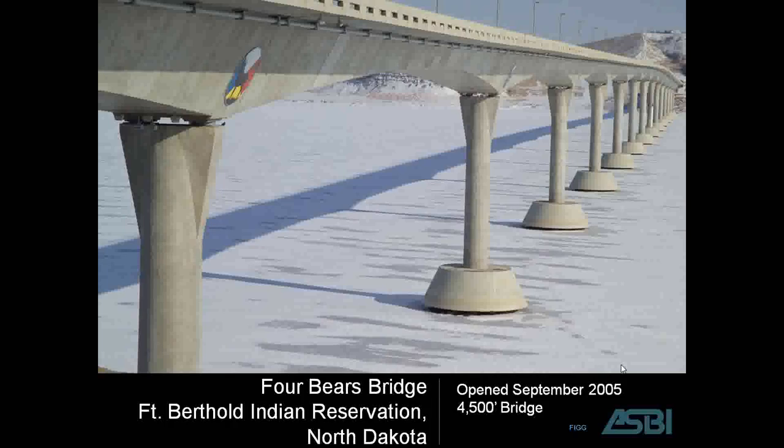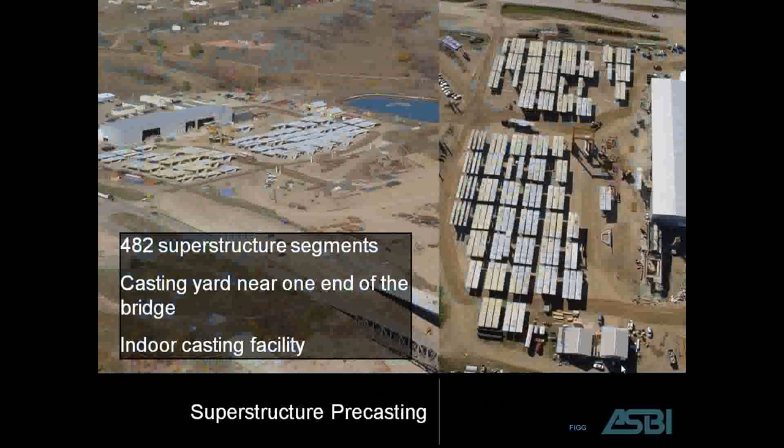This bridge also has an integral wearing surface, and you'll hear me talk about this throughout the presentation today. Several of the bridges I will show will have this type of wearing course. It's a 2-inch additional concrete depth that's applied to each segment, and that acts as the integral wearing surface. After the bridge is constructed, it's ground down for rideability, and that integral wearing surface provides protection from chloride intrusion, and in the future could be removed and an overlay applied if it ever becomes problematic.